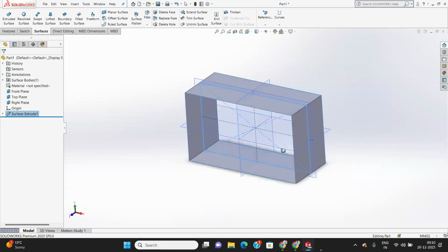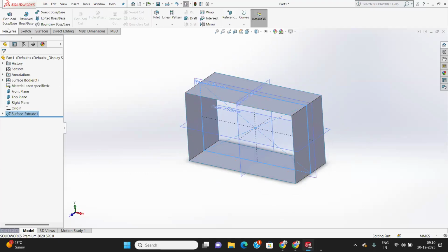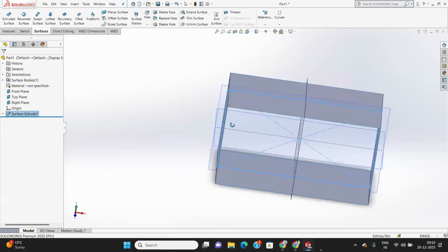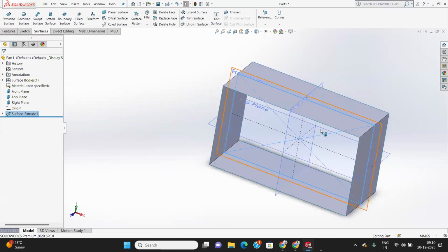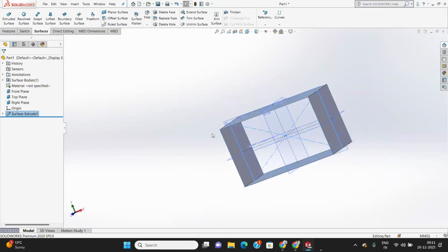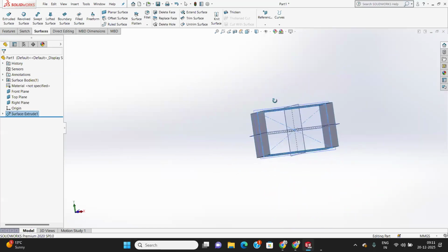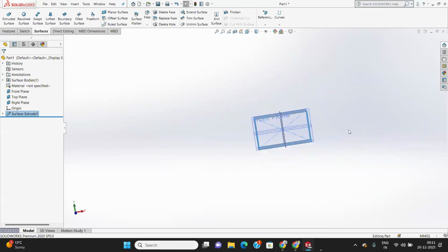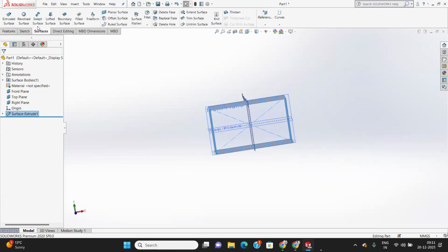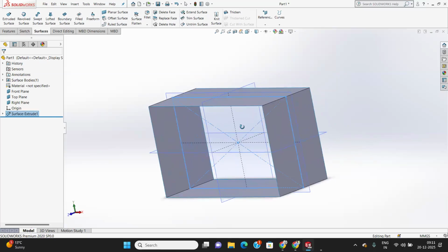This is called the surface modeling, where you work only on the surface. And feature is the solid modeling, where you work on the part of the solid space. Inside is plain, but we make a big hole, because this is used for making sheet type metals. In the feature, we can also do a thin form and then make a hollow part also. But in this case, we directly make it without any operation.